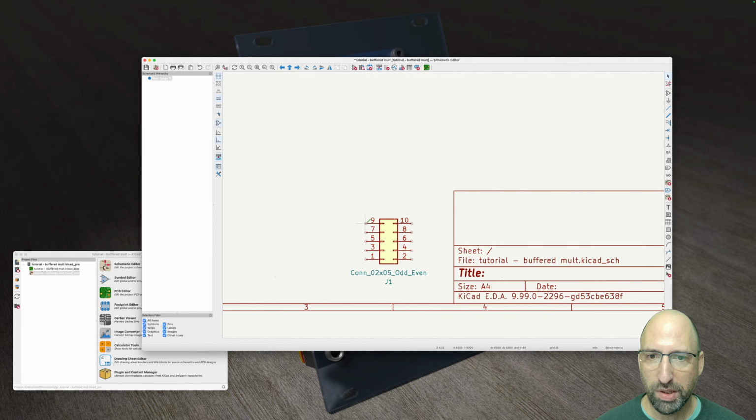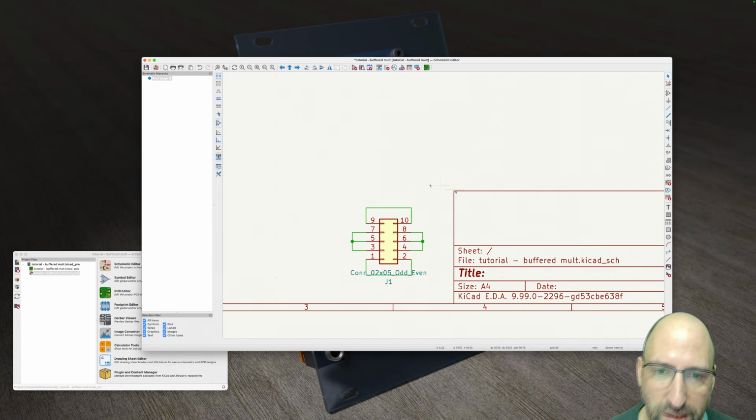So how do we do this? We're going to need to connect both sides, because these pins do exactly the same thing. So for the plus and minus 12 volt pins, and the ground, we're going to want to make a little bit of a trident over here, because all those pins connect to ground. Same on this side. So we're just going to click and create some wires.